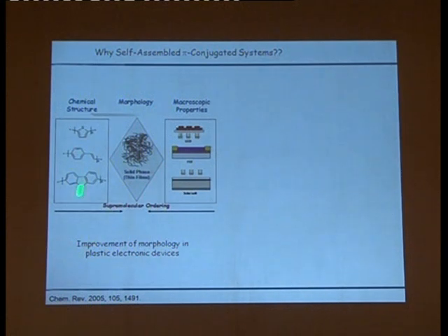Most organic electronic devices use pi-conjugated polymers. But one of the problems with pi-conjugated polymers is that it is often very difficult to get them completely pure; you will always have some structural defects. So one alternative is to work with pi-conjugated oligomers, which are monodisperse and can be made synthetically completely pure. Then you can control their organization and get higher efficiency out of these devices.